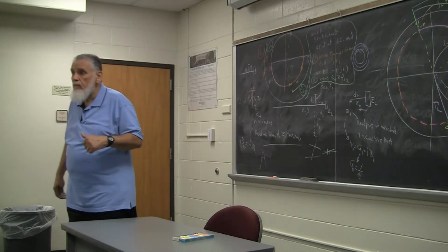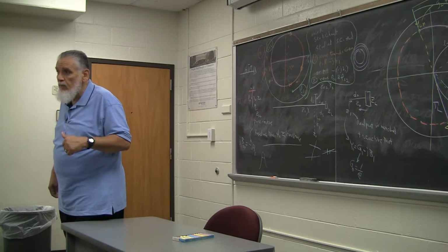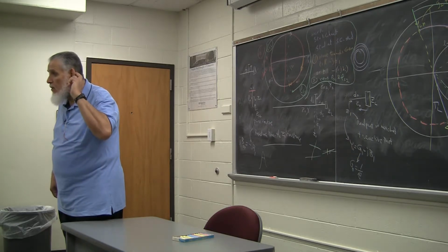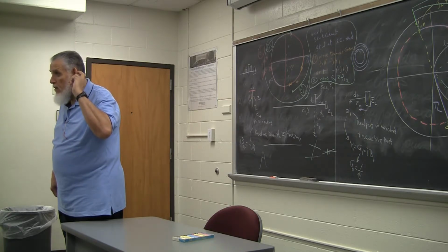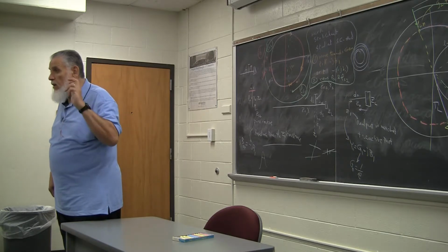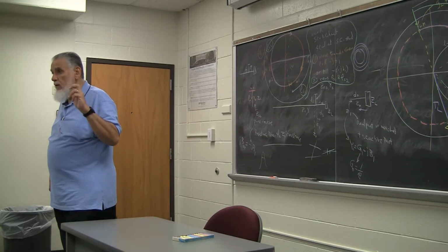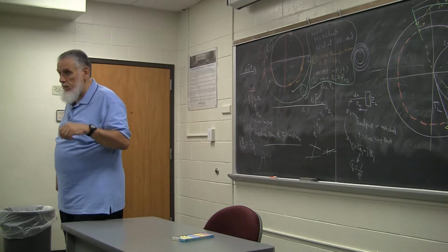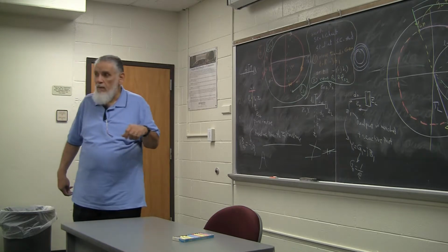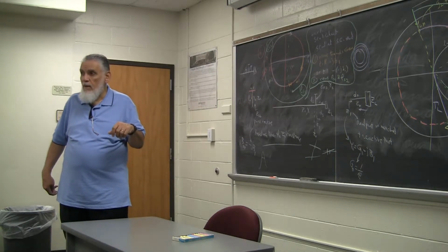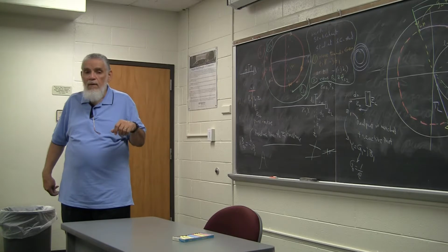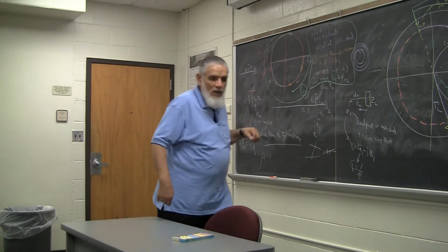Also, on the Smith chart, if you have Q equal to 1, 2, 3, those arcs you can draw. You can draw arcs on the Smith chart that show you different Q levels. So if you move from the center towards the outskirts, you get different Q. Talking about the eye shape. Yeah. So you have arcs that go from OC to SC and give you different Q levels as you go from the center to the outer one. Okay, I see what you're saying.